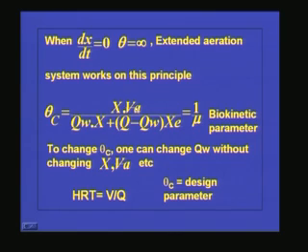So Va is the volume of the aeration tank and X is the biomass concentration per liter or per meter cube, divided by, and what is the biomass wasted from the system, that is nothing but Qw into X. Qw is the quantity wasted into what is the concentration of biomass in the wasted liquid, plus Q minus Qw into Xe. This is coming out along with the effluent from the secondary treatment plant. So it is nothing but 1 by mu, okay, because we have seen that what is this mu? Mu is the specific growth rate.